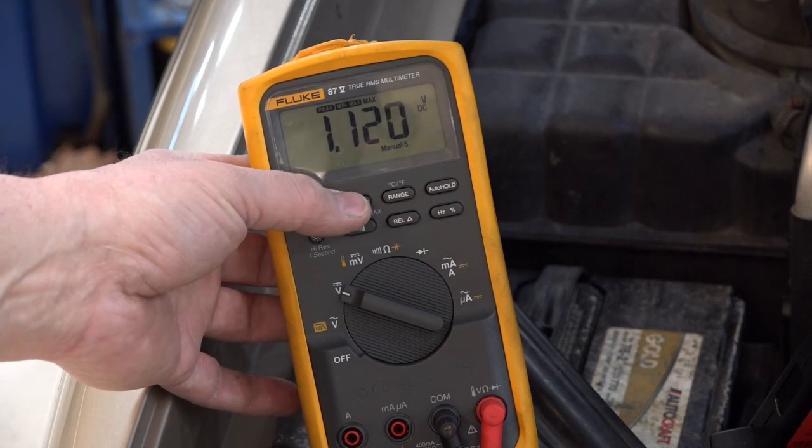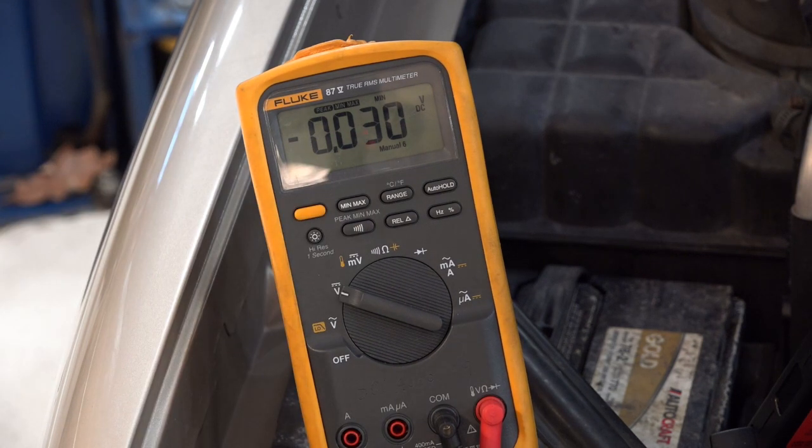So let's see what our minimum is, negative 0.03. That would be actually 300 milliamps there in the negative direction. So it's possible either my zero is skewed a little bit, or maybe I've got a motor or something going on here and actually providing a little bit of AC voltage or voltage in the negative direction. The other possibility could be a solenoid that is pulsing on and off, which could give me, again, a voltage reading in the negative direction. I don't know what kind of solenoids are on here other than maybe the starter, that's going to be pulling about 11 amps though. Next, I'm going to go ahead and probably just put a current probe using the scope